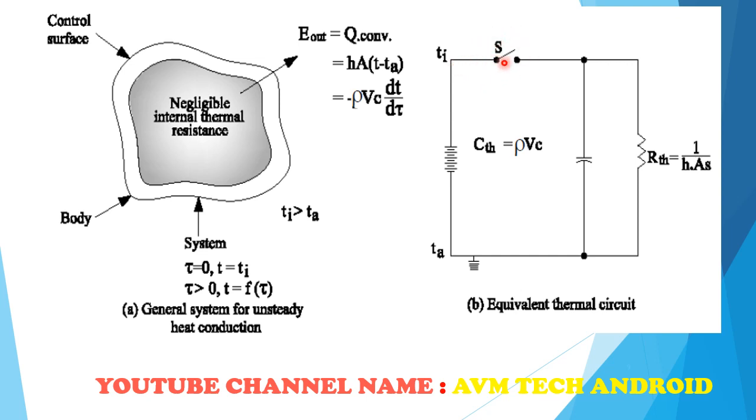the circuit is completed, and the heat will start to flow from the system. The resistance offered, that is the convection resistance, is 1 upon h into As. And as soon as the switch is kept open, the heat does not flow through the resistance, and all the heat will be stored in the capacitor. So the heat that will be stored in the system is Cth, that is rho V c, that is density, volume and specific heat. I hope this equivalent circuit is also clear to you.